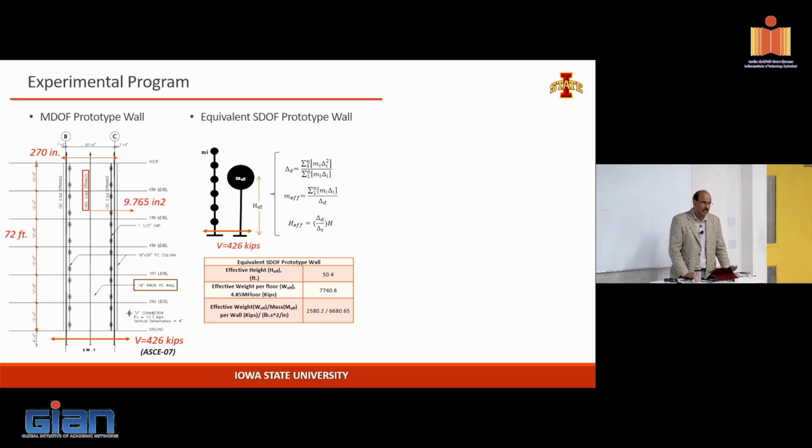I think that paper will speed up work when you... Yeah. So there are some papers. If you're going to do, I think, the single rocking wall, for example, you could use it for non-seismic quite comfortably, but the anchorage issue is one we need to address. So if you're going to do any test, the first test I would recommend is to get some strands and wedges and do an evaluation on that. How can they survive? You can do a fatigue evaluation, you can do those things.